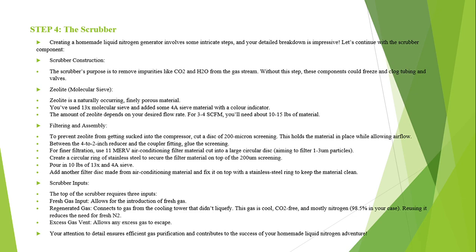Scrubber input. The top of the scrubber requires 3 inputs: fresh gas input, regenerated gas to reduce the need for flash N2, and an excess gas vent to allow any excess gas to escape.